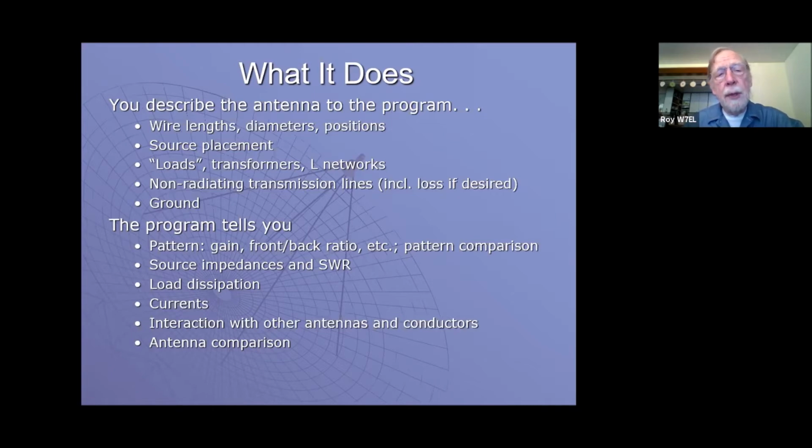You can put in non-radiating transmission lines, which you can include loss with if you want, and ground. And then the program will tell you the gain, front to back ratio, pattern comparison, source impedances, SWR, load dissipation, currents, and so forth. It's really great for modeling interaction with other antennas and conductors.